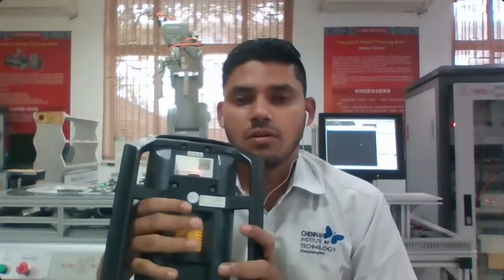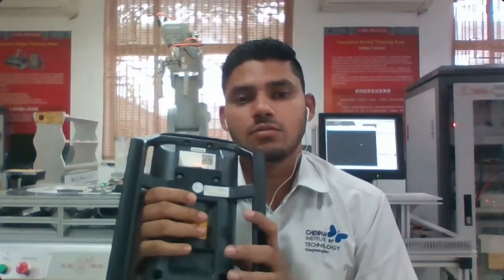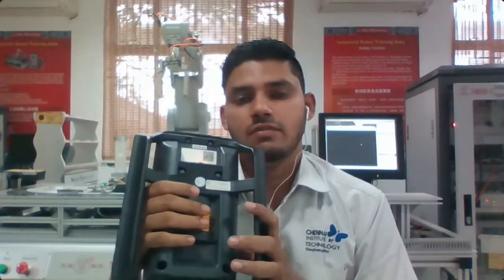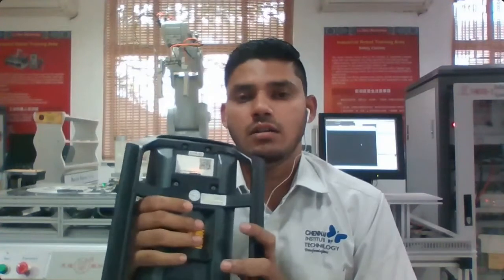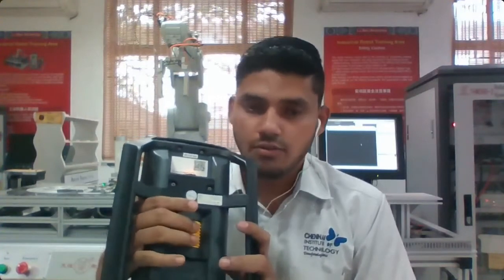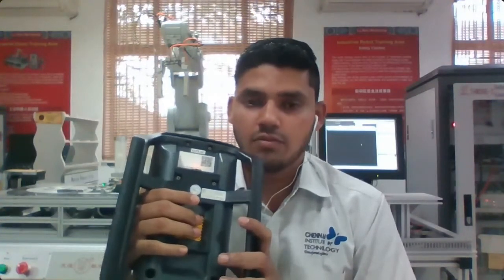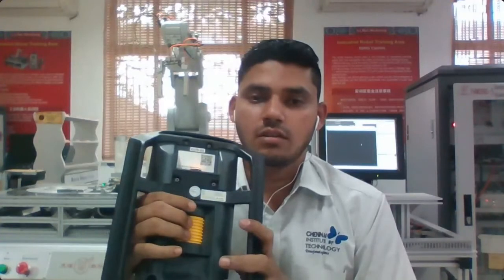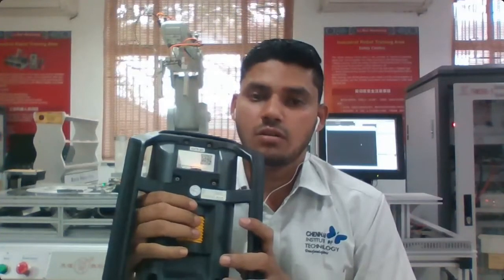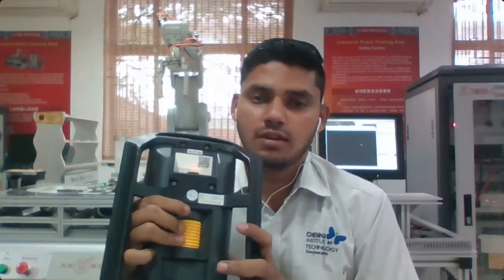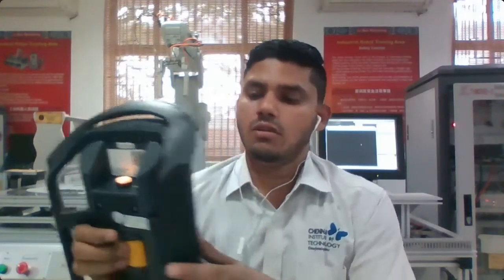This is actually one of the safest methods to handle this robot. The purpose of this key is that you should hold it in a middle position. You should not hold it loose, or hold it tight. It's a middle position. If you hold it in this middle position only, you are able to work anything in this robot. If you are not holding that position, the robot will not work.